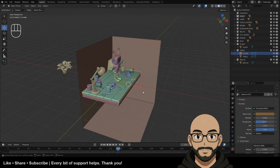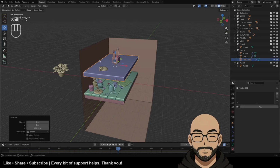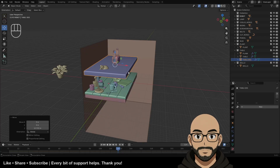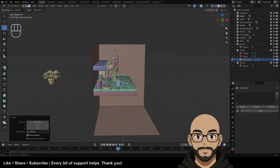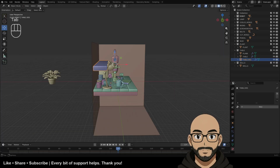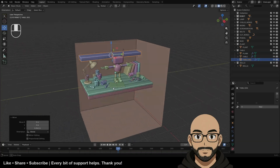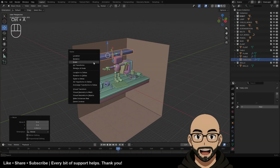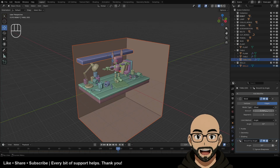Anyway, let's duplicate this table and make this a shelf up here, so we can put our plant in. So I'm going to push this back, then place the object and move this up. There we go. And we can hit Control A, apply scale. Because this has a bevel as well, you can of course adjust that bevel.